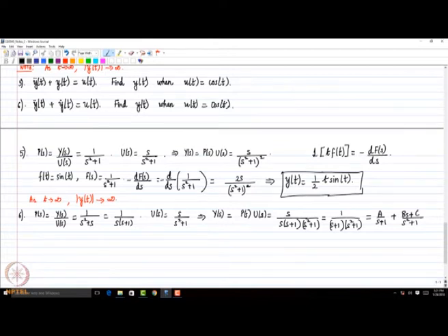A pole is a characteristic of the system or the plant. Here the cancellation of s was a mathematical operation which came in due to the specific nature of the input that we have. In general, we have a more subtle idea called pole zero cancellation. We will come there when we go deeper into control system design.